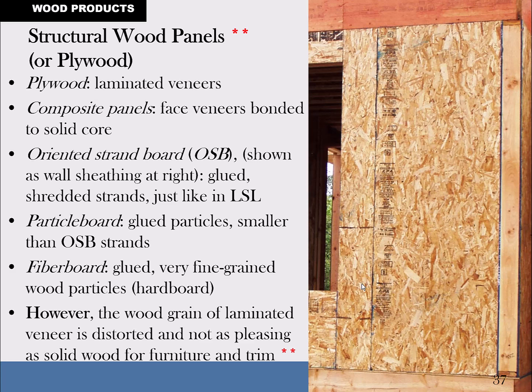It's a very efficient use of wood products. So again, you don't need big trees to make this stuff, whereas with plywood, you do need decent quality trees so that you can peel the log for the veneer. So I'll have to show you how that works. Particle board, again, is a very efficient use of wood because they're taking sawdust, which is always so plentiful, and turning that into a solid piece of particle board that's quite dense and heavy. Again, because that glue is heavy.